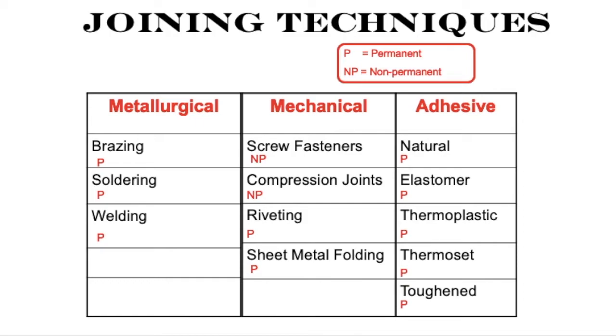And then the answer, since you can't answer me now, would be it is usually important where a product is expected to undergo modification, repairs, and things like that. So you would go for a non-permanent joining technique because you want to put components together to maintain it or to modify it at a later stage. Then you guys can think of other reasons as well.